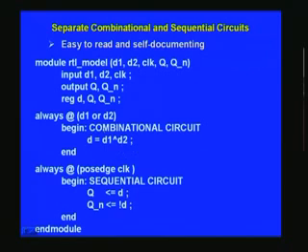And for improving the readability, you can have this. It's a good practice to have this. And this does nothing more than take the exclusive OR of two inputs and assign it to D, and that's what this logic is doing. This is just a D input for a flip-flop, and the flip-flop is written in a segregated block here, which is also an always block, and the action is taken at the positive edge of the clock.